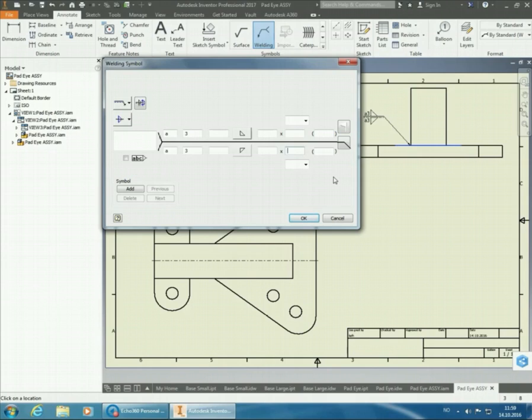There is also a possibility of setting the length of your welds. You can do that in these columns here. So you can set the length of the weld, and you can also set, for an example, if you have several meters of parts that are going to be welded together, you can set a short length, and you can set the amount of intervals that you're going to have. Another possibility is if you have a circular object and you're going to weld all the way around it, you can press on the corner of the welding symbol to get a circle there. Then it's going to show that the welder has to weld all the way around.